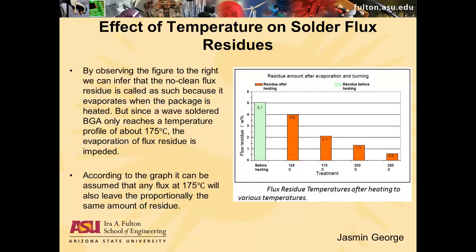Thank you, Thavone. I will now cover the effects of temperature on solder flux residues. As you can see, the graph shows the residue left after heating the package. The first bar shows the package before heating, and the others the effect of different temperatures on the residue. The purpose of no clean flux is to automatically vaporize or remove flux when the package is heated. But as you can see, it is not quite true.